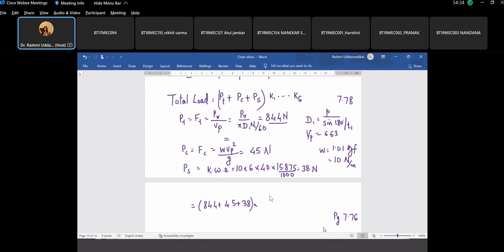If I consider load with mild shocks, my value of K1 comes out to be how much? For load with mild shock, assuming the compressor is creating mild shock, what is K1? 1.25. Next is the factor for distance regulation. Either we are having adjustable supports, or the drive with the idler sprocket, or the fixed center distance. Now if nothing is mentioned, we assume this is having adjustable support, or this is the simplest of condition with K value as 1.